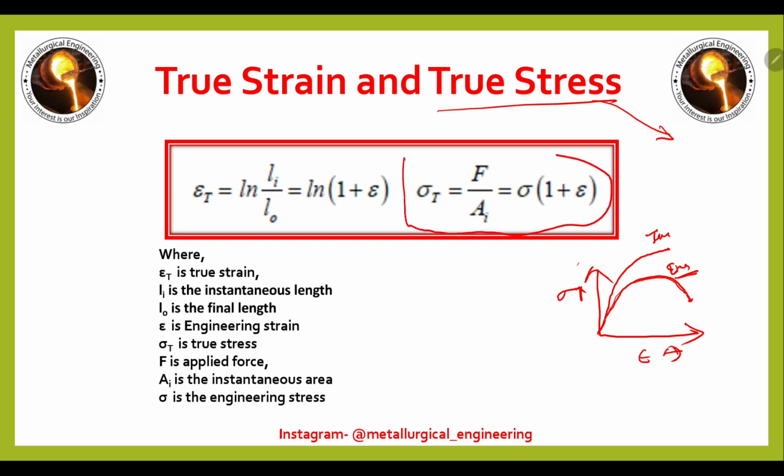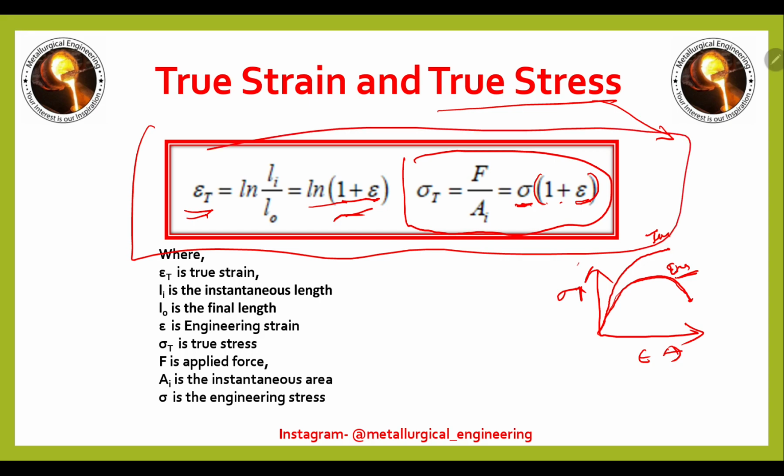The true stress is equal to engineering stress multiplied by 1 plus engineering strain. While the relationship between engineering strain and true strain is: true strain equals the logarithm of 1 plus engineering strain. So you can remember this, one numerical you may get in the exam.